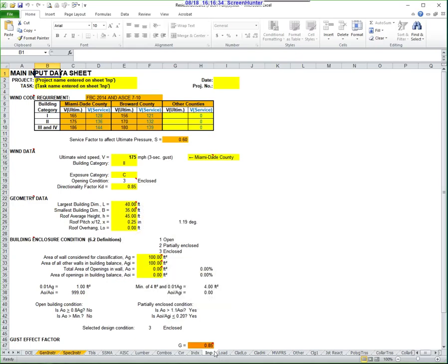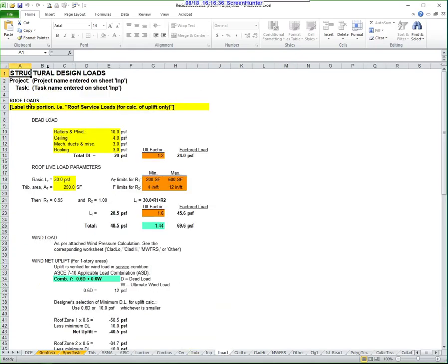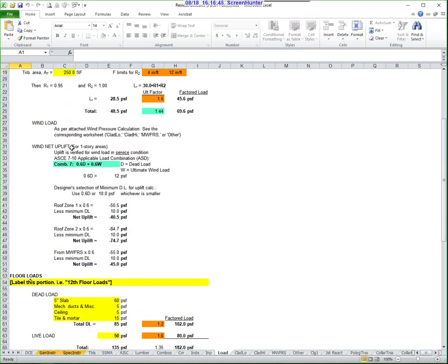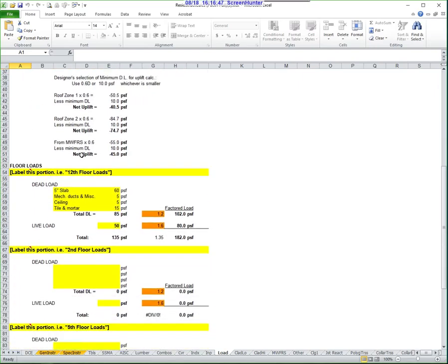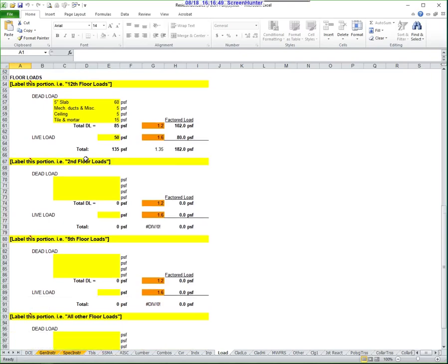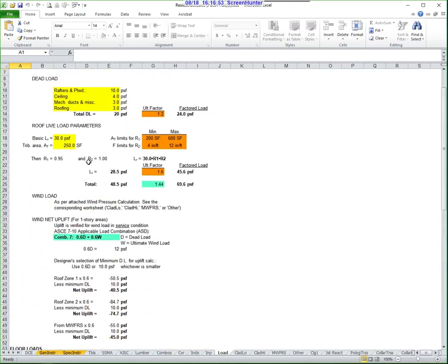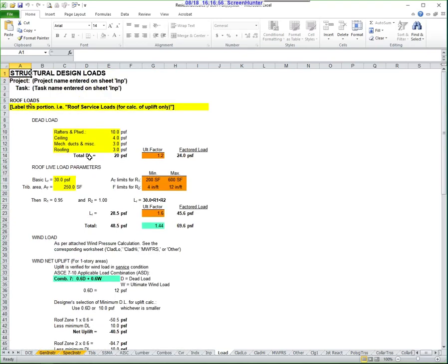Load, gravity load data, and summary of applicable wind pressures. Input data on this worksheet is for general control of gravity loads, linked to several design modules as applicable. It is intended to be used for any material to be designed, but it also provides strength design factors for concrete design in accordance with the ACI 318-10 code.